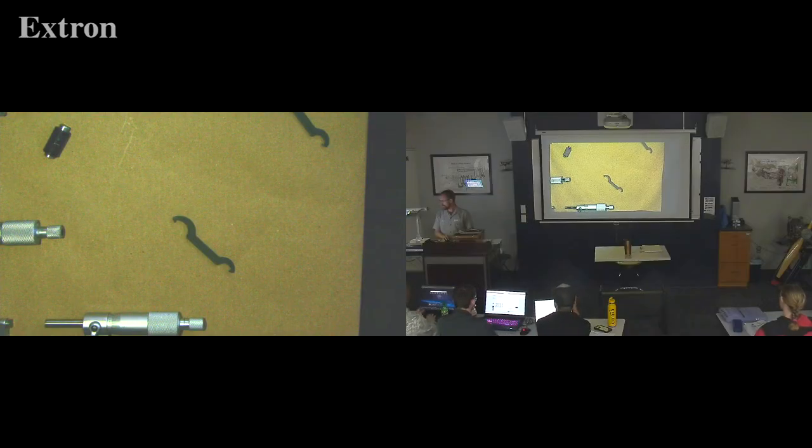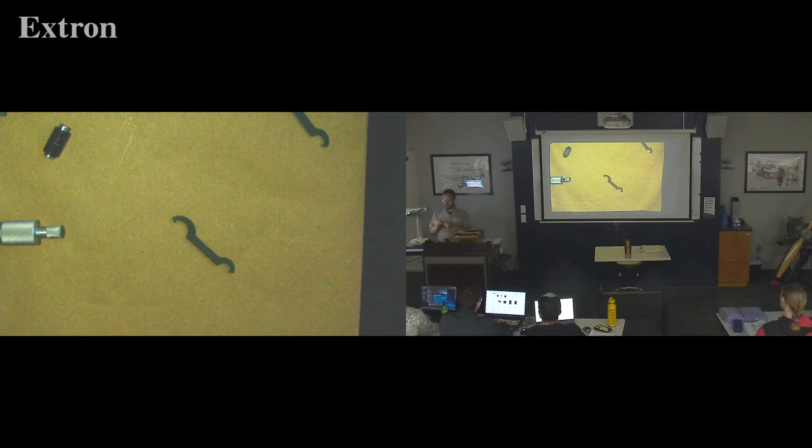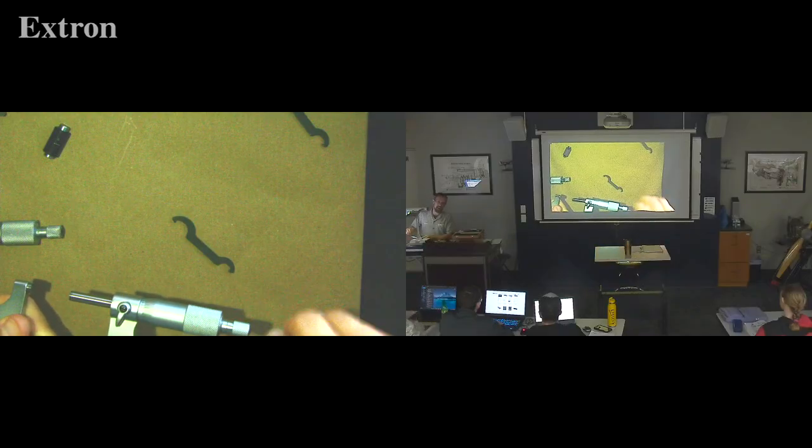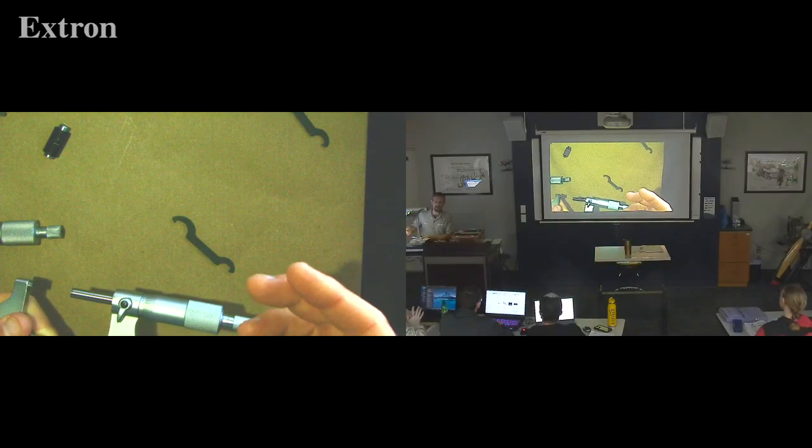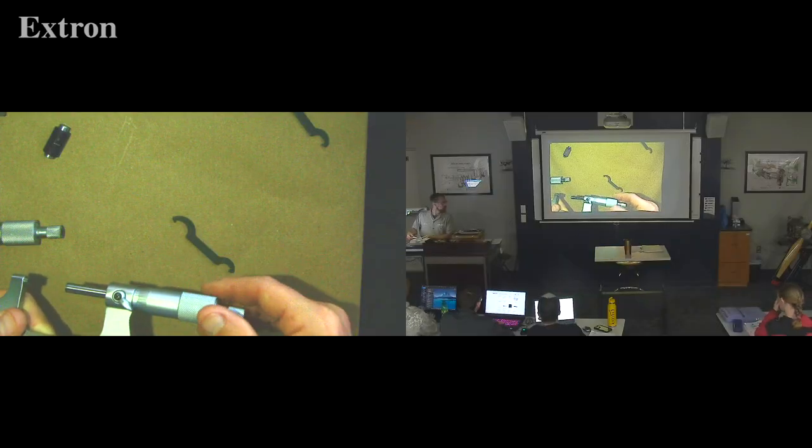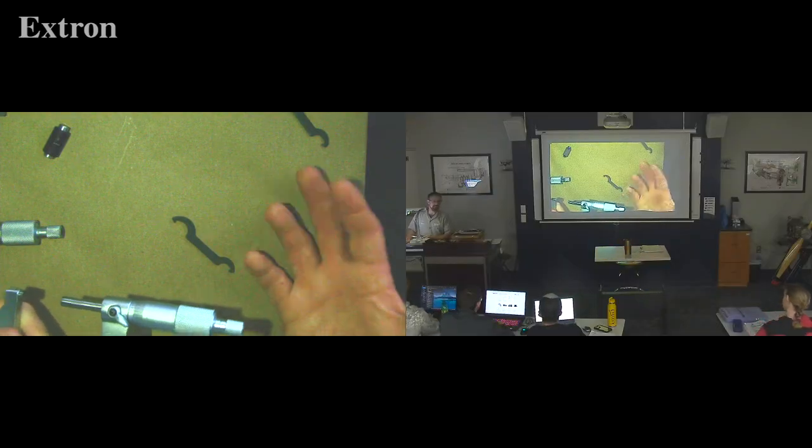How often do you have to calibrate the tool? Here at SMAT, I do it every time I touch it. Because if I'm using it continuously, I'm good. But the moment I put it in the box and I let somebody else, even if it's, hey, Shane needs it for just a minute. Now, I trust Shane. But his touch may not be my touch, okay? So when he gets over there and he tightens it up, or he leaves it locked and then he tries to tighten it up, now it's going to turn it. Got my issue there? So it's going to throw off the calibration. Did he mean to do that? Did he catch himself? No.